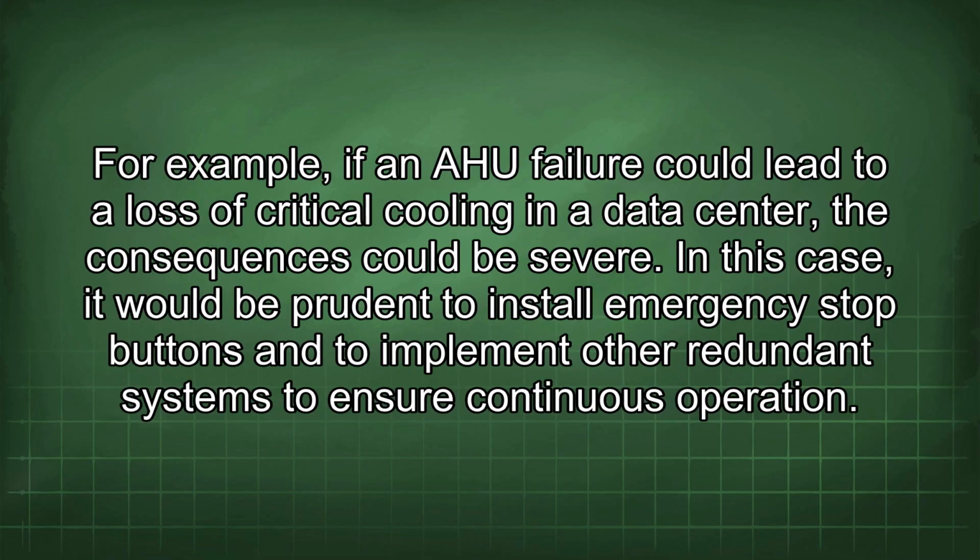For example, if an AHU failure could lead to a loss of critical cooling in a data center, the consequences could be severe. In this case, it would be prudent to install emergency stop buttons and to implement other redundant systems to ensure continuous operation.